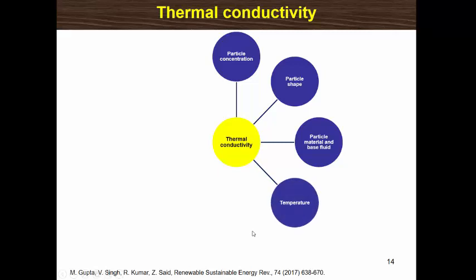The thermal conductivity of nanofluids depends on the temperature. The thermal conductivity of nanofluid increases with increasing temperature, because Brownian motion and clustering, which are important factors affecting the thermal conductivity of nanofluid, are significantly influenced by temperature.